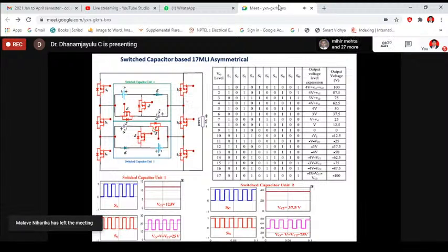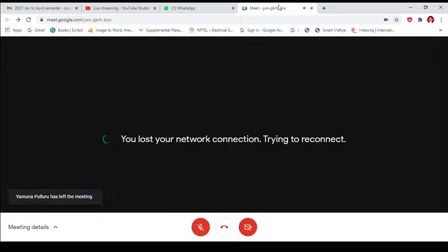So this is our arrangement using this switched capacitor unit. We are able to generate 70 levels. See that this is unit 1 and unit 2. In unit 1, let us take, I have fixed Vc1 at 12.5 volts. During discharge time, V naught, the output voltage, doubles. That means from 12.5 you are achieving a 25 volt waveform. We have tested with